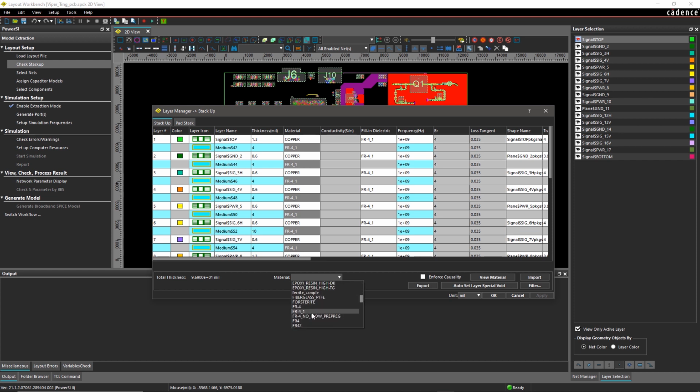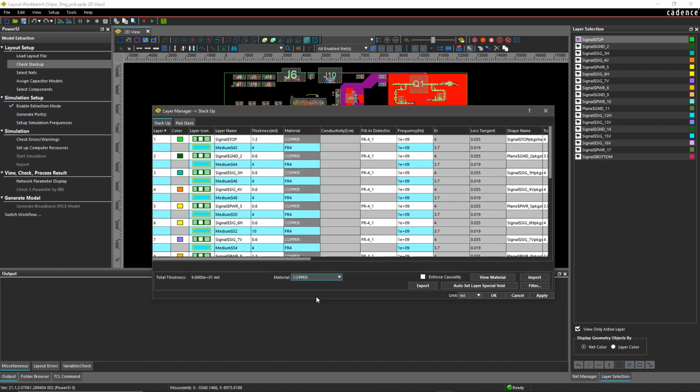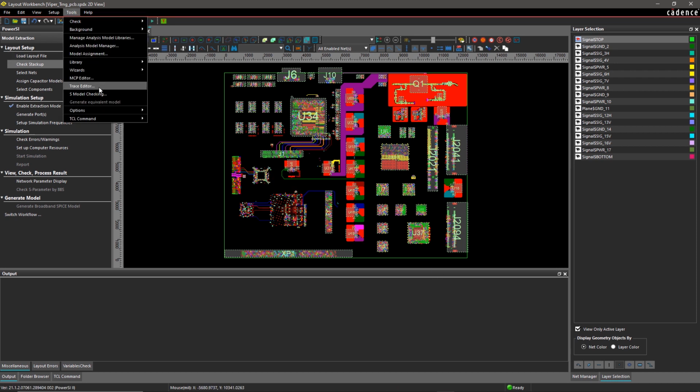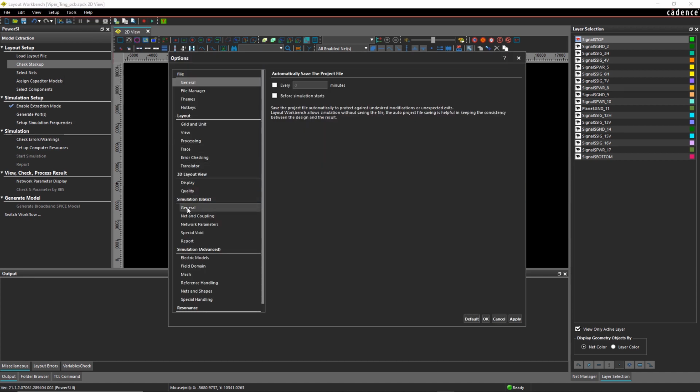By managing crosstalk or interference between signals, defining the stack of materials, and using decoupling capacitors, you can maintain PDN impedance. Within the stackup, you can also specify the conductivity of signal layers as a function of temperature.